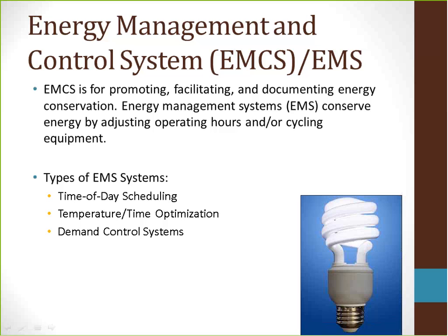The third and final is demand control systems. With these systems, all of the functions of temperature time optimization and time clock controls are incorporated in a system that also controls electricity demand by cycling pre-selected loads on and off as demand approaches preset limits.